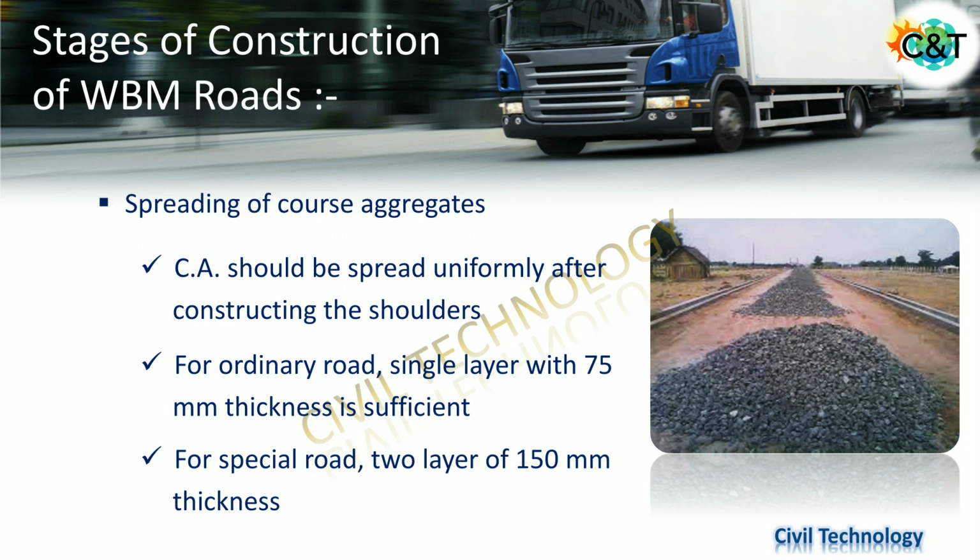Do not follow blindly. Please do not follow blindly. Always refer to your pavement design report. There they mention what thickness you have to give for the coarser aggregate layers and screening material layers and all that. So refer to that on your site. This is a general criteria, so you can easily understand.